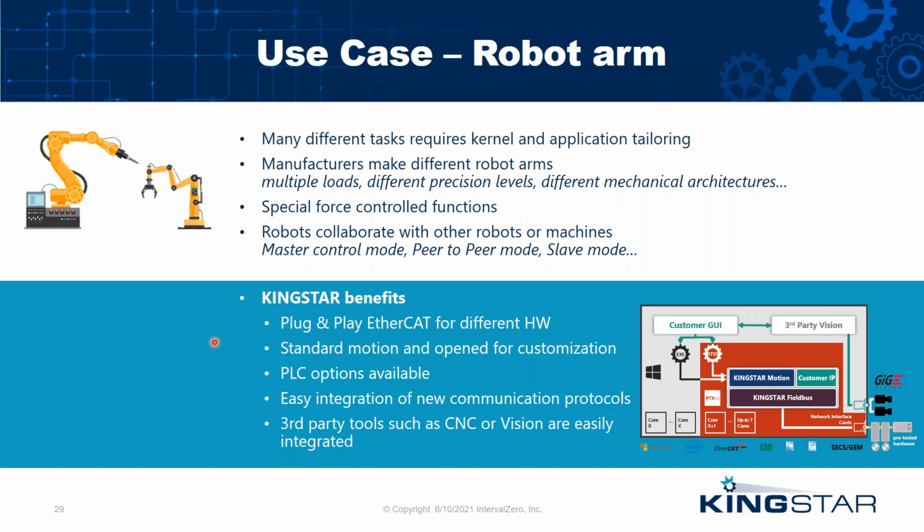One more thing to note is that when you do collision avoidance, you need real time, because if you are using a normal protocol, normal Ethernet, to exchange this information, you do not know if it is outdated or not. Therefore, in that case, you may want to use a real-time protocol such as EtherCAT for communication between the two peer-to-peer machines.